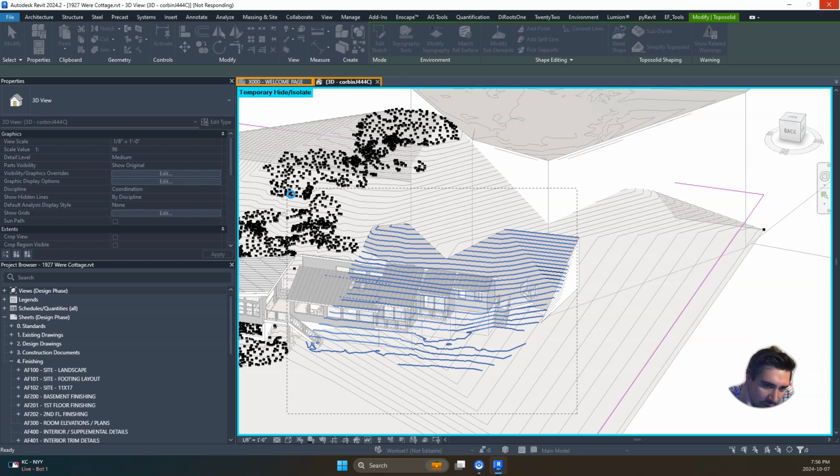The other thing I find too is if you have areas of topography that you're not too concerned about, when we're doing these extract contour lines, which I might do for the large piece of topography, we can actually only extract the primary contours so that we're trying to add less detail. And usually how I do that is I focus around the building itself. I add more detail in that area, and then when we get farther from the building, we lessen the amount of detail. So let me pause it right there and we'll wait for this to unfreeze.